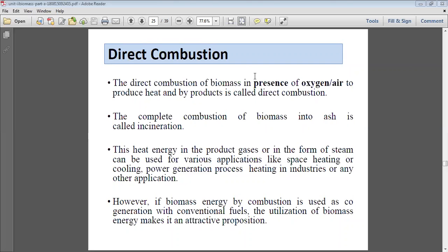In co-generation, biomass is basically a waste product; otherwise that matter would have gone to waste. So that organic waste is being treated and used for co-generation with a thermal power plant, and we are going to save coal, 20 to 25% of coal, even in a single plant. That is for a plant running 24 hours a day, 30 days a month.